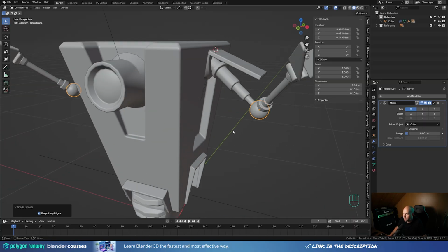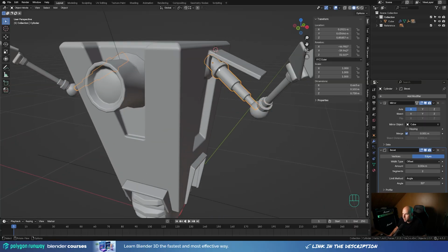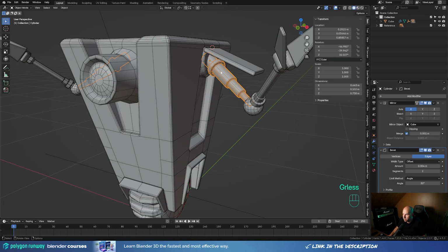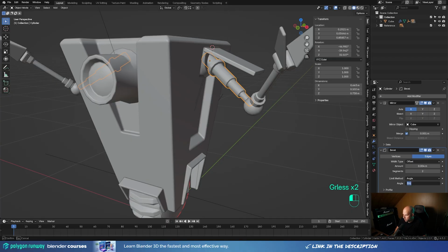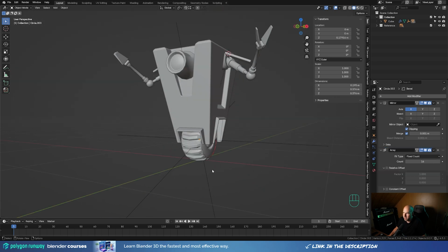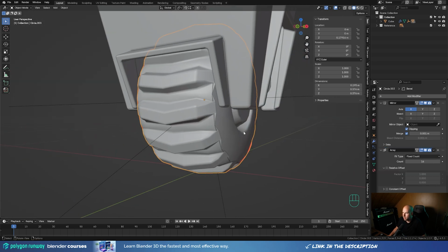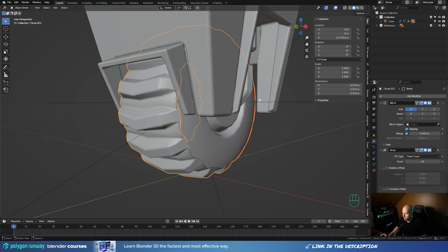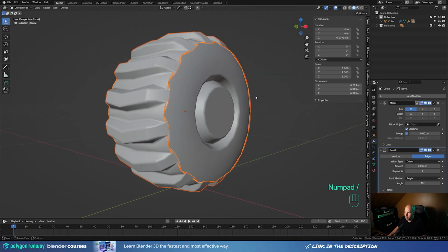We have this result. Now let's adjust this a little bit, because the bevel modifier is catching some of the angles I don't want to see there. So let's increase the angle to 45 degrees on the hands and here as well, and on these cylinders. So if you have two selected, you can just type 45 and then hold Alt key and enter, and that will apply your new setting on both objects. And I can see the wheel is a little bit messy, so let's fix that. We can add some more geometry there. So let's select the wheel. With the side, hit slash on the numpad.